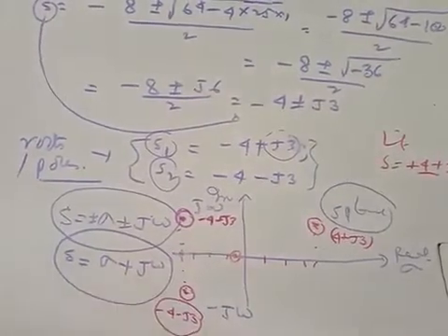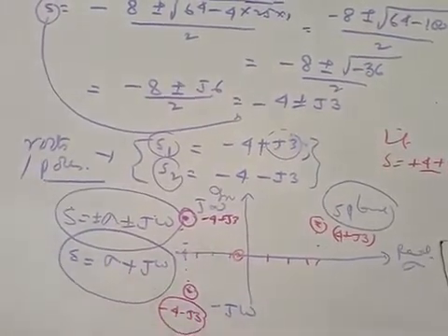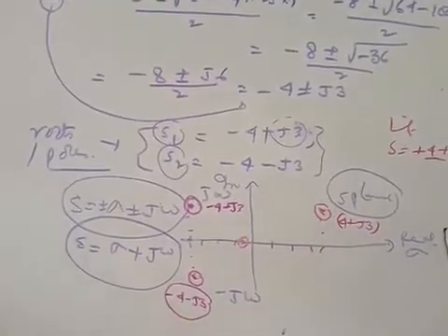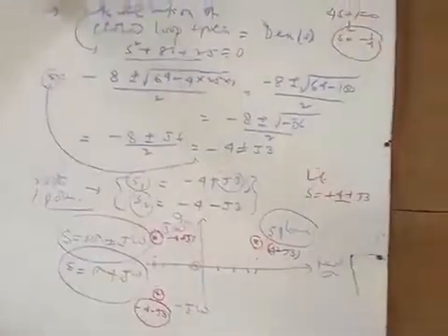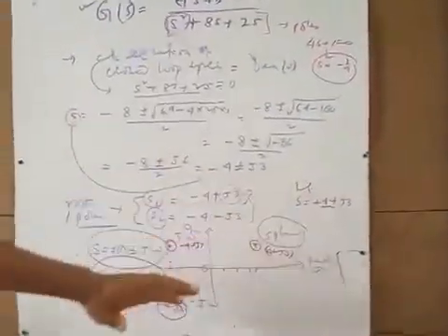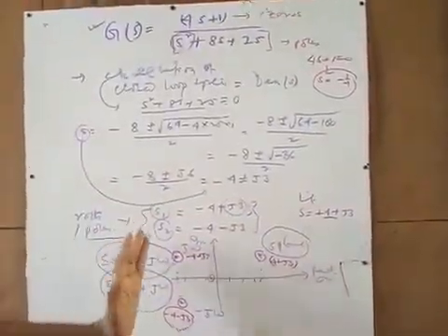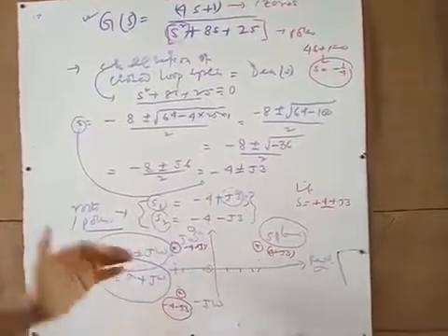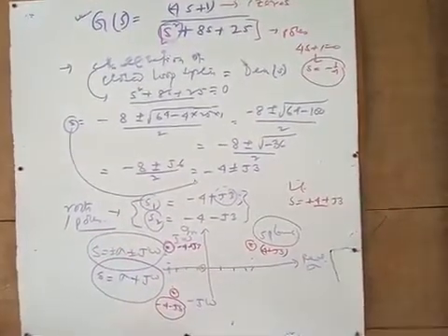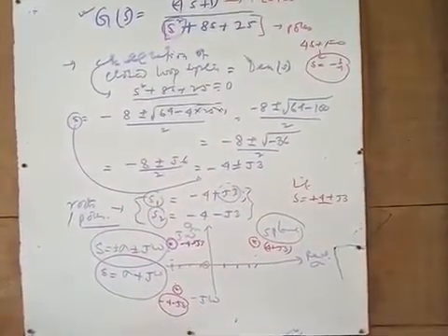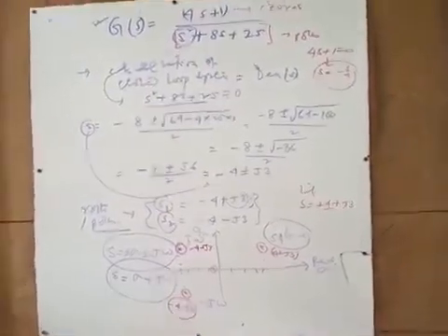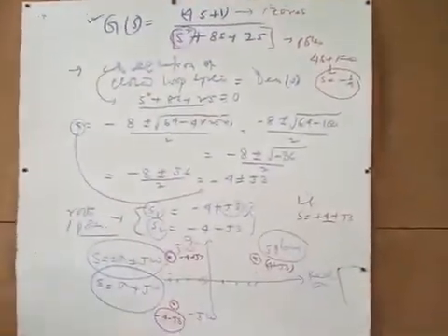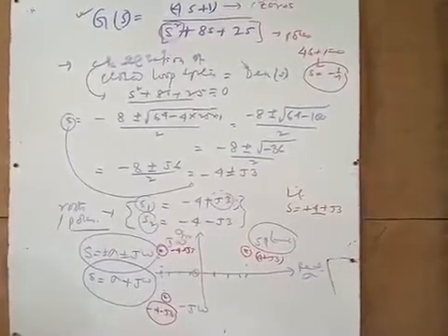So this is how on the s plane you have to place all the poles and zeros of a given system from the closed loop transfer function, right? If you place the roots, that means poles and zeros, on this s plane, then there will be a way to get the stability criteria, and the stability criteria will be discussed later on. Now our aim is to get the roots.